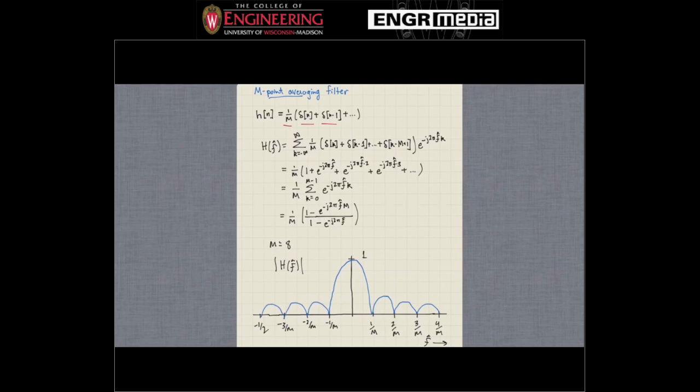and so on, a bunch of spikes. So that would just look like this. It's the impulse response of the endpoint moving average filter, dot, dot, dot, all the way out to M. It's got M points. And we can plug this directly into the definition of frequency response.